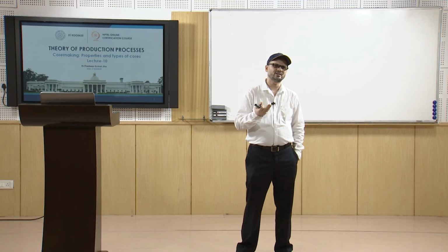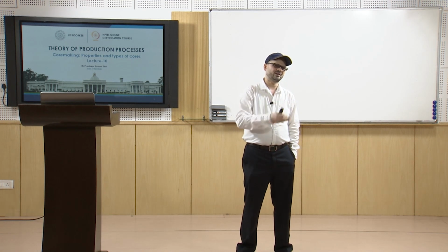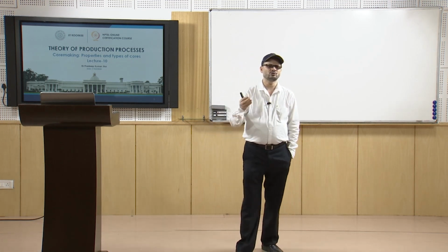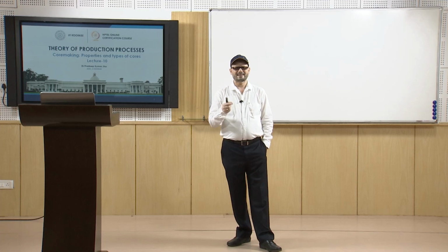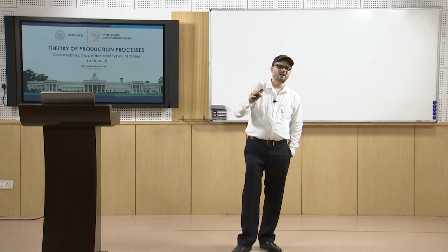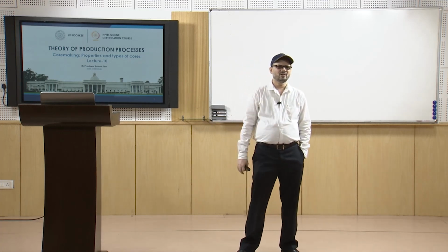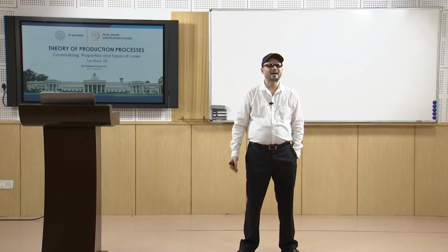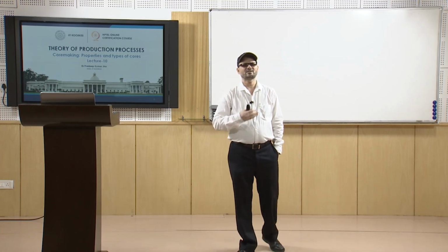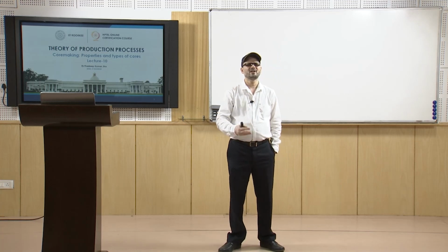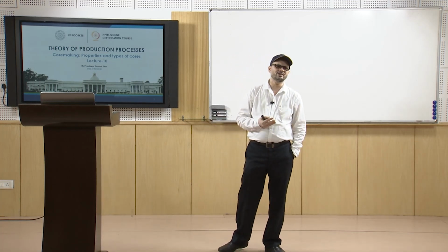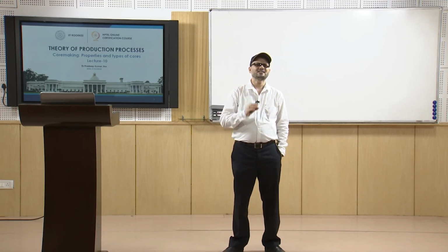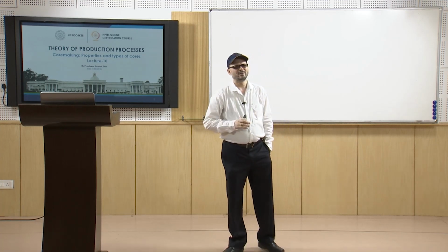It is like when we are removing the core knockout by hammering or so, at that time it should easily crumble, so that it does not stick, or you do not have to hammer it repeatedly or with higher forces. So, in that case this property is known as friability.